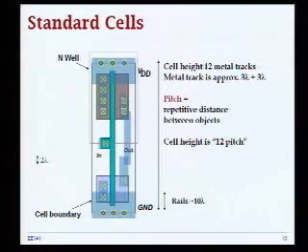Normally, in the lower level metals, you have the same width of the metal and the same distance between two objects on the same metal layer. So you have your rails over here, then you have N well for the PMOS, and the cell height is about 12 metal tracks, and each metal track is about 6 lambda.